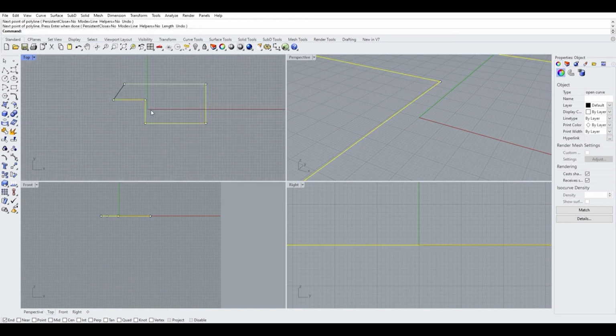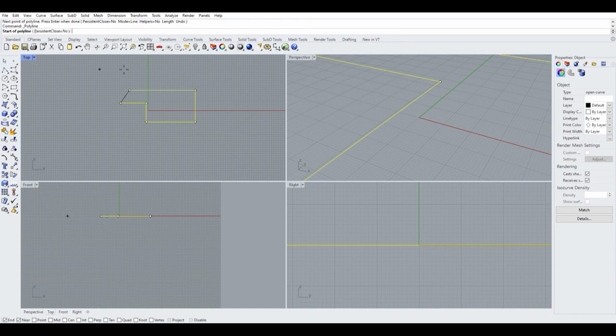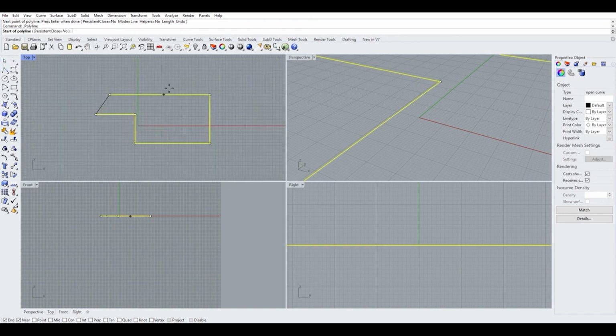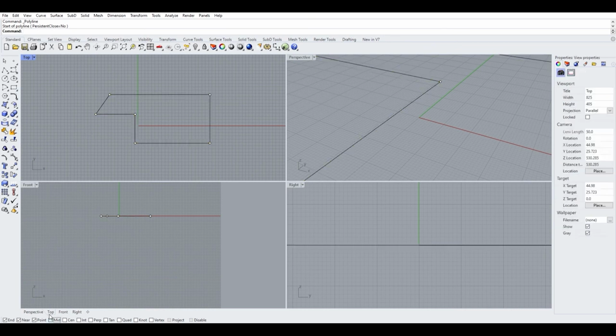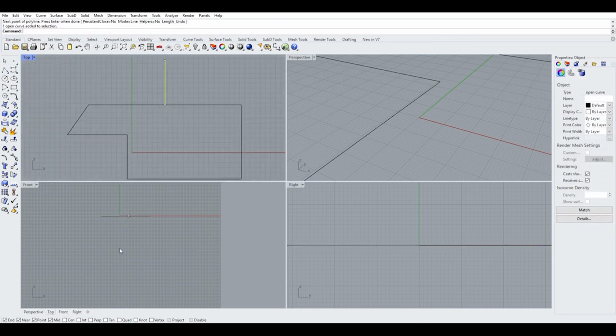All right. Now, next up, we have a lot of different options for what I'd like to snap to. Near snaps to almost anything, so make sure it touches it. So if I hover anywhere near there, it says near, which means it'll touch that line. Point is useful if I want to snap to a specific point. Mid allows me to divide something in half, so I'm going to use this line there. Hover near the middle, and it'll say mid, so it marks it. That's the midpoint of this specific line.